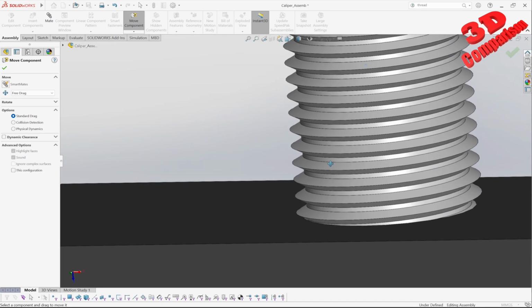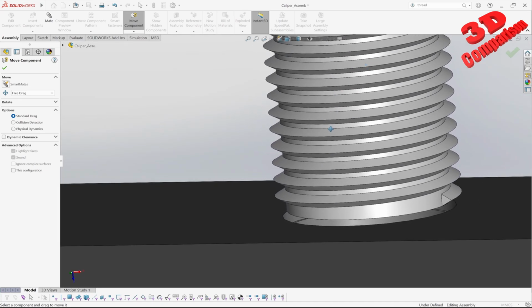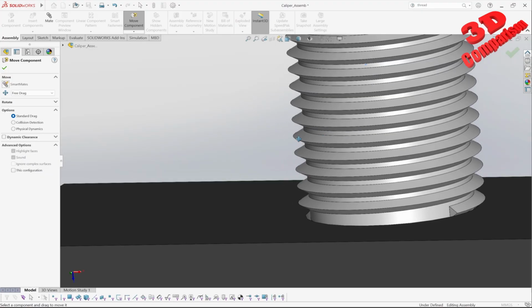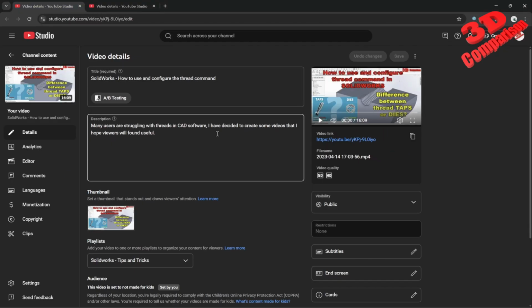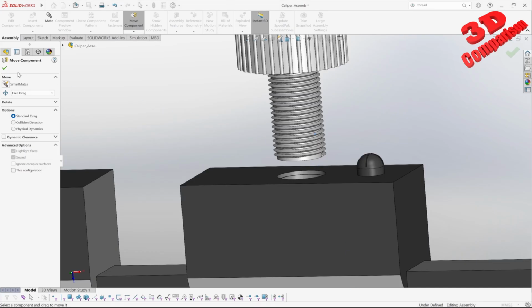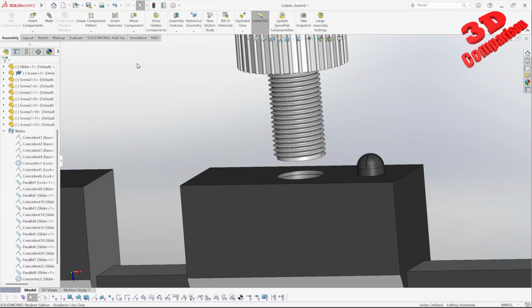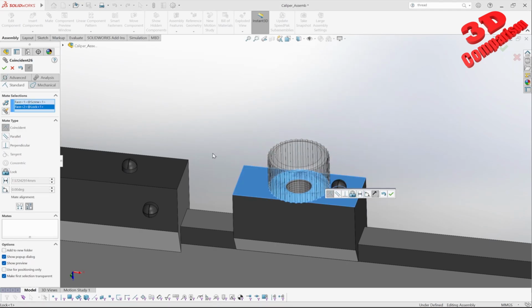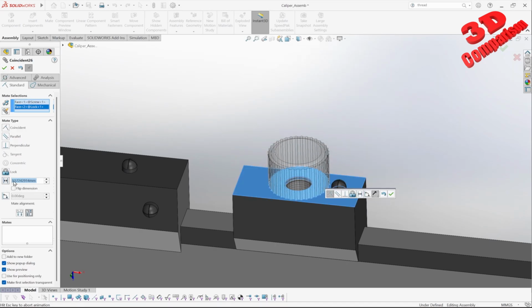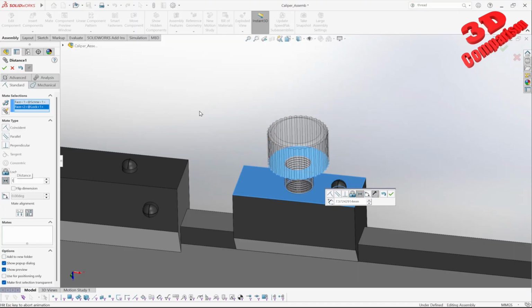As you can see over here, the overall size for the fillet and the thread is not that well defined, so that should also be further adjusted. You can also check my additional video regarding this, so how to use the hole and the thread features in order to define added depths or dies, depending on what you are designing. And let's see over here, I will want this to be mated like this, so we're going to have a little bit of collision, but I'm going to leave it like this. Maybe I'm going to leave a little bit of space, let's say 1 millimeter over here.